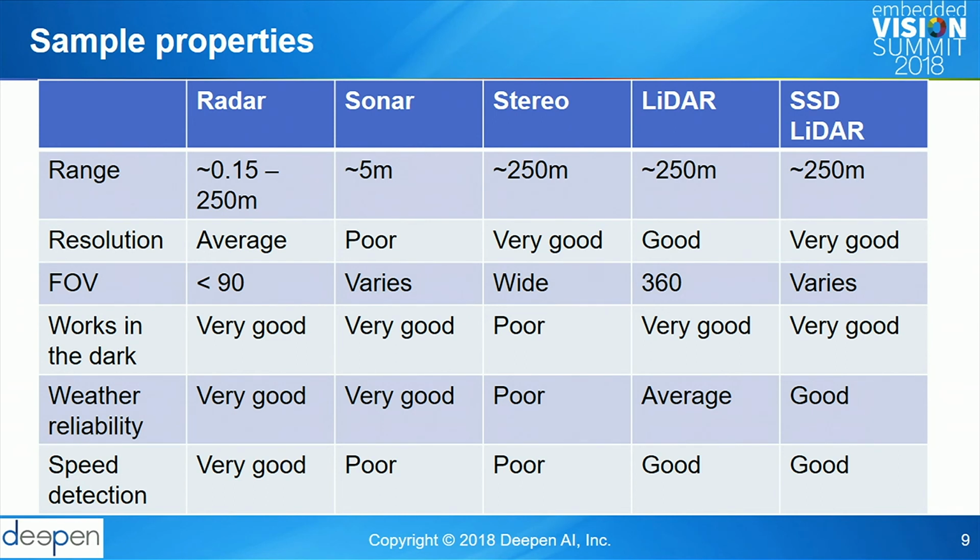And even if it's a stereo camera, actually, the depth from stereo, a lot of people in research look at it as a solved problem, but actually stereo depth has a lot of issues on its own too, because you need some feature anchors to enable you to get the depth accurately. So if you wanted to get the 2 centimeter level of accuracy, I think light is the best physical technology available for that kind of thing. Ultimately, we think for level 4, where you don't have a human taking any control of the vehicle, you cannot get away with camera alone. Tesla and others don't believe so. I guess I'll be proven right in a few years. Thank you. No problem.